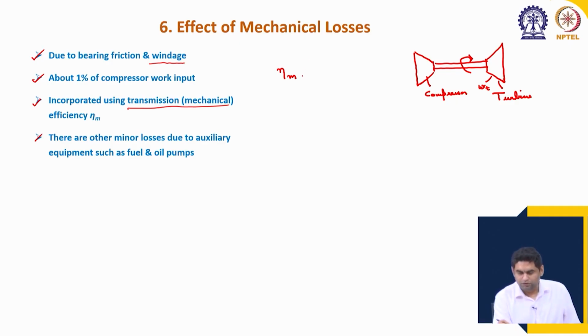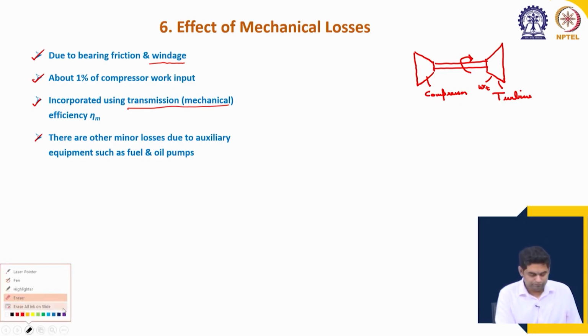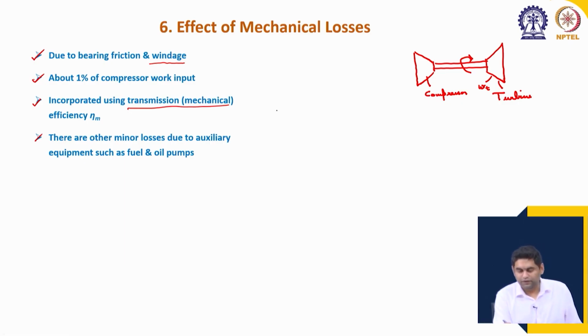Let us define it in another way, because otherwise there will be confusion. Let us say, what is the work needed for running the compressor, WC. The work which is needed for running the compressor is equal to Cp of air into T02 minus T01 for a standard process.